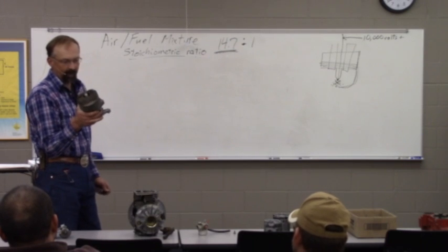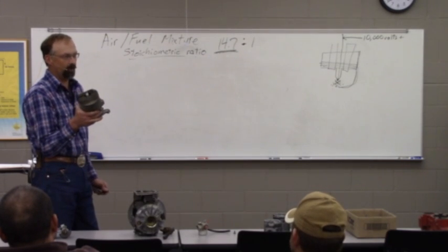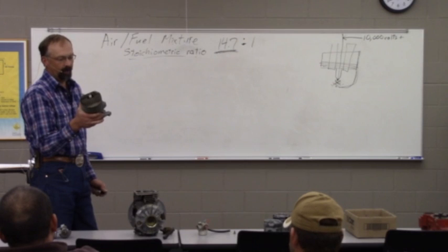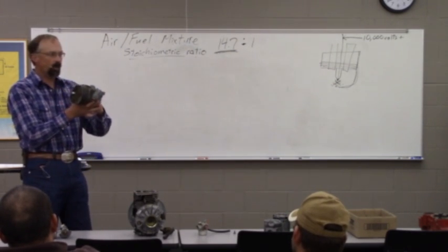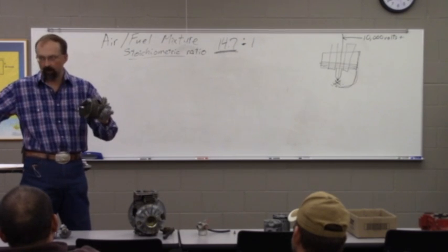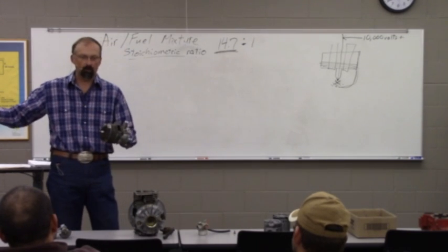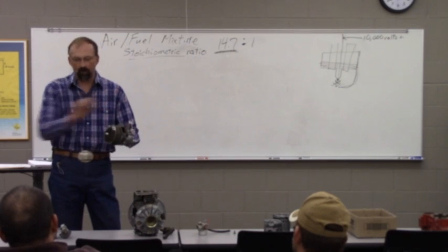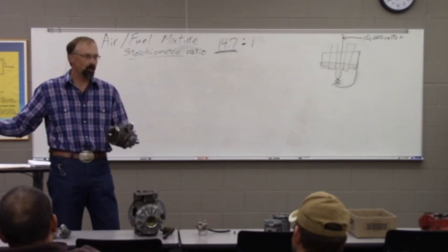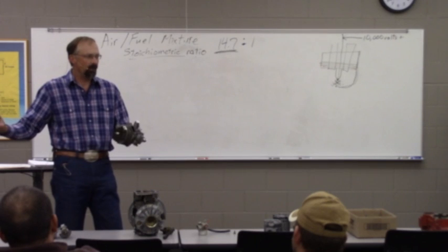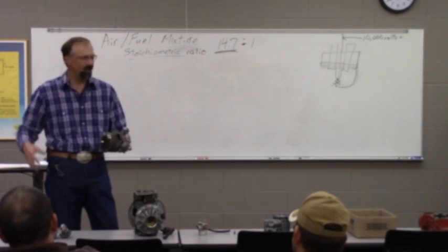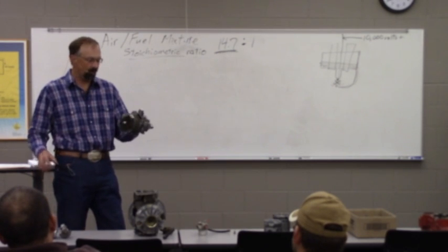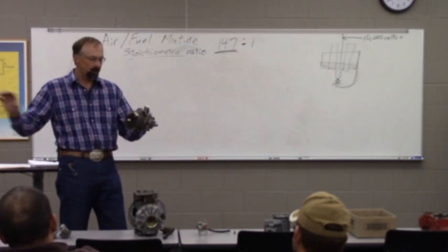That is exactly the same thing we're doing with our radiator. In the radiator, we're actually passing water through tubes. You may not realize it, but a radiator is actually a bunch of tubes. Most all modern radiators, the tubes are running horizontally, and they're what's known as cross-flow radiators. In years past, we had downflow, or vertical flow, where the tubes would go this way. I haven't seen hardly any of those in a long time. But anyways, the tubes will go this way.